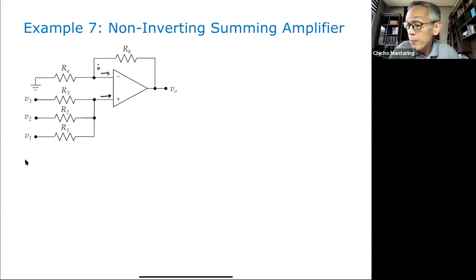So I minus is equal to 0 and I plus is equal to 0. And then we apply nodal analysis. So let's do that. The voltage here is V plus. The voltage here is V minus. Let's apply nodal analysis at the non-inverting input. So KCL at the non-inverting input.